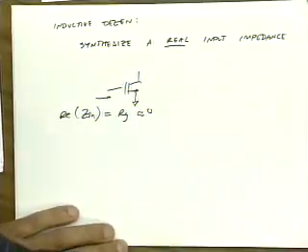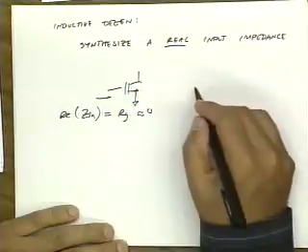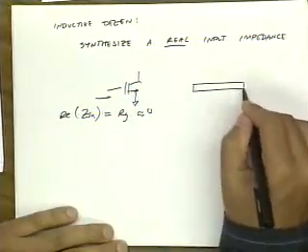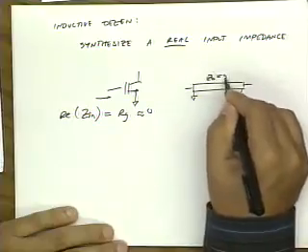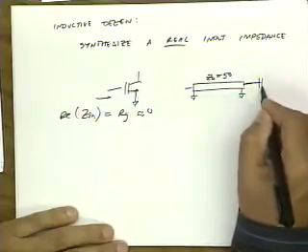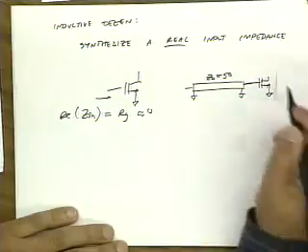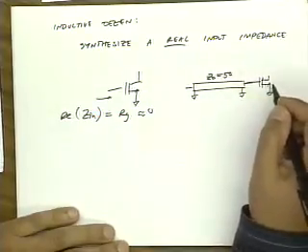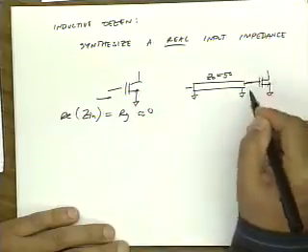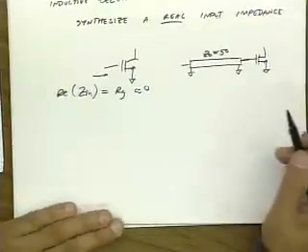And let's say I want to drive this with a 50 ohm source resistance. Let's say I have a cable or a transmission line which has a Z naught of 50 ohms, and I want my transistor to terminate this with 50 ohms. Well, that's pretty hard to do with the transistor.